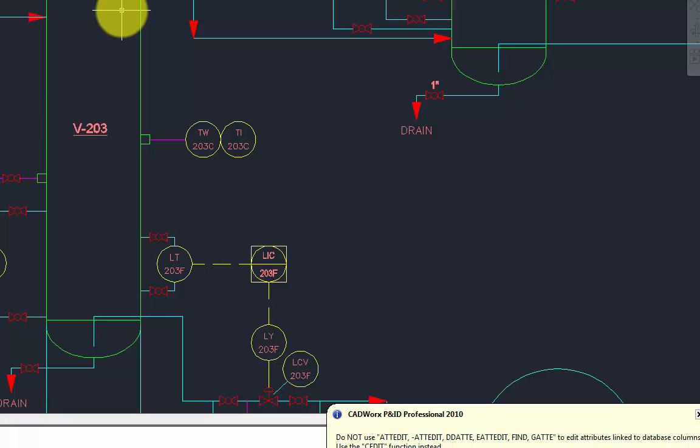I could select all 20 of them. It would add 20 control valves to your database. Okay, great. So you don't necessarily have to retrace the entire drawing to upconvert that. At times that may be easiest, but in general you can upconvert and use the existing graphics and just add intelligence on top.